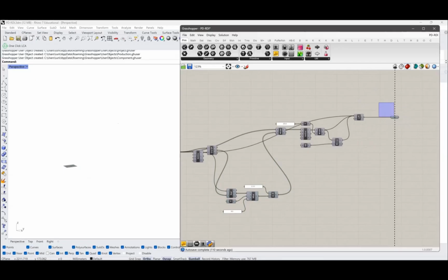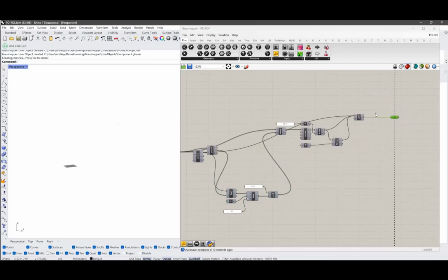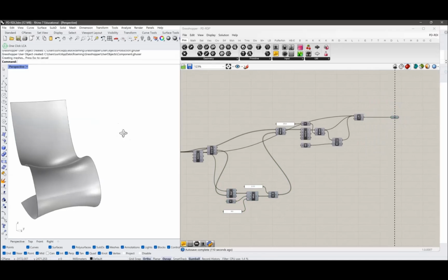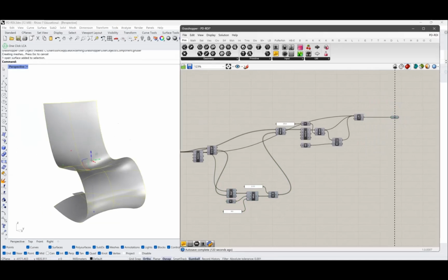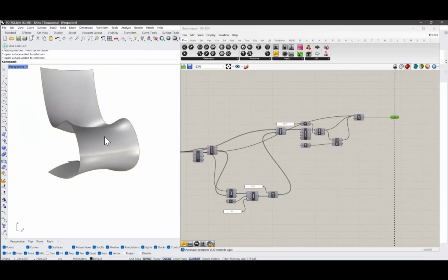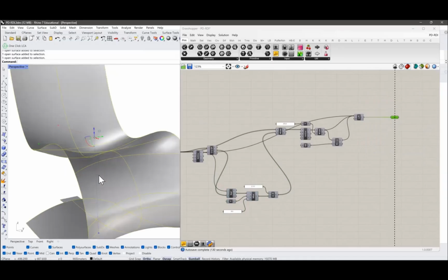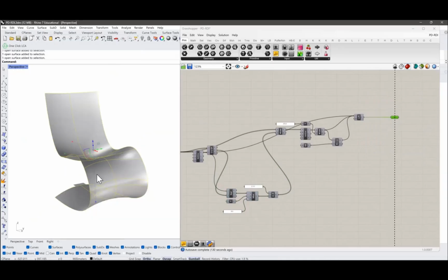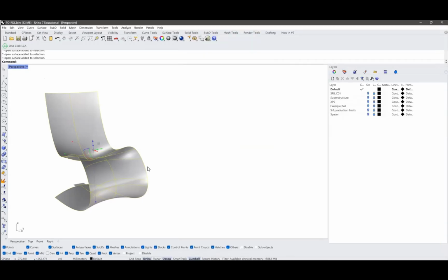They are not real. That's why some of the models have, under the right click, the very important button, bake. So if you bake it, you transform the geometry from the virtual reality of Grasshopper to the reality of Rhino. So now it's like a solid object, let's say, not the solid. Yeah, it's better to say that it's a shell. It's not the solid object, but anyway, it has some real representation in Rhino. So then with different tools that you can see inside Rhino, you can modify it, whatever.